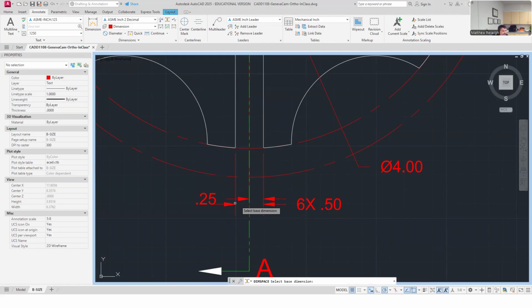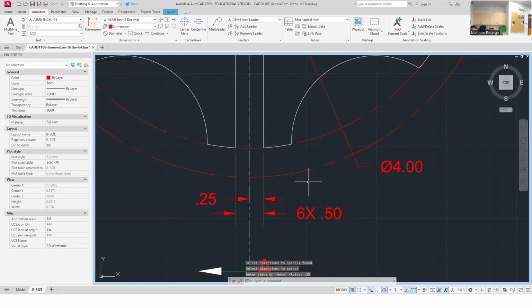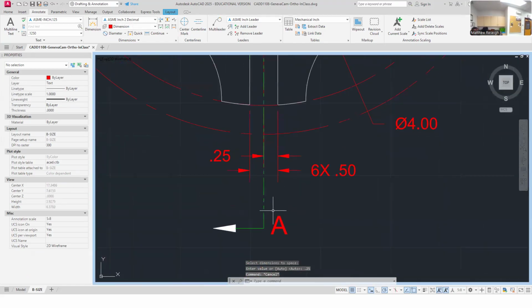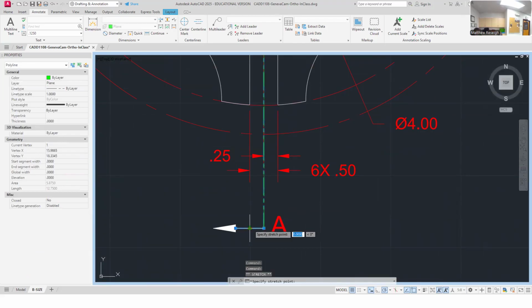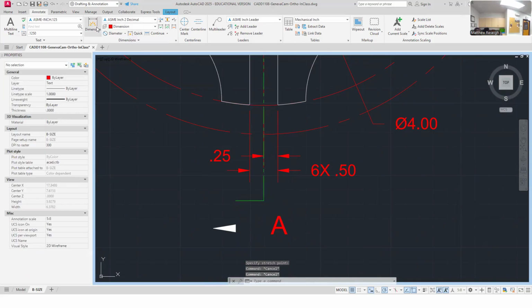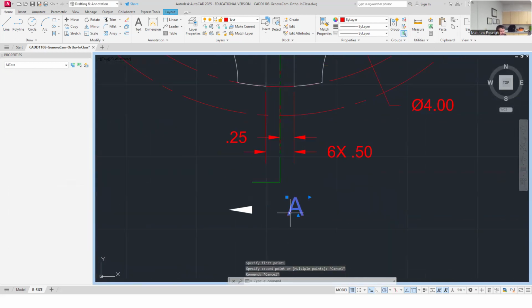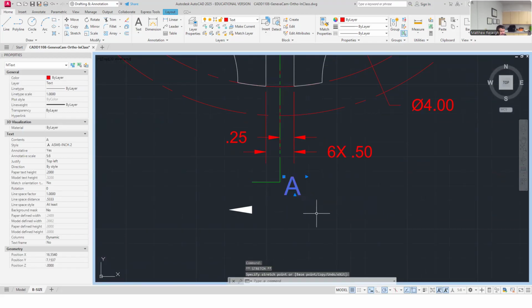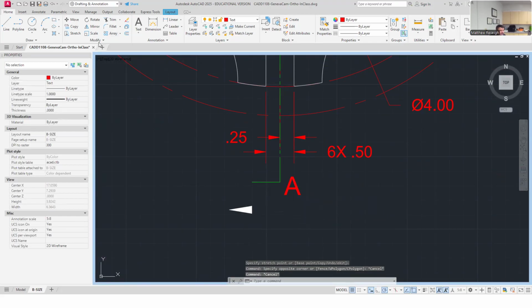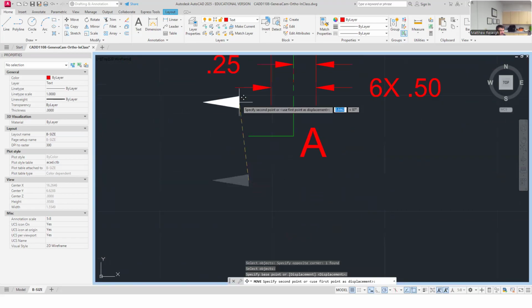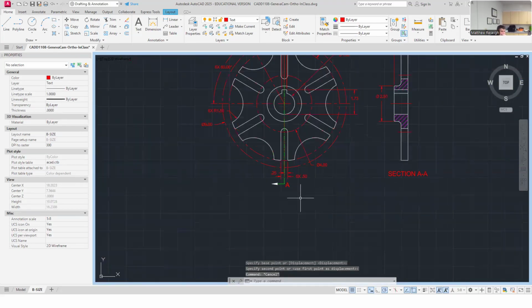So I'll use my spacer, and I think I'll say that it's 0.25 away, like that. I like that. And I think this one's a little far away, so I'll probably stretch this in. I never did look up the book, but in my mind, I'm thinking that these are sometimes roughly about a 1/2 inch away. I'm only 3/8 away, but a 1/2 inch seems like a good distance. Here's my view label. I'm about 3/8, so that'll work. And then I'm going to move this thing by this base point up to this. Yeah, that looks pretty good.